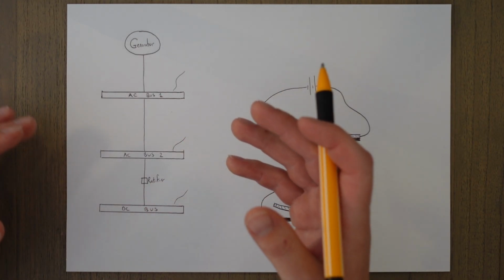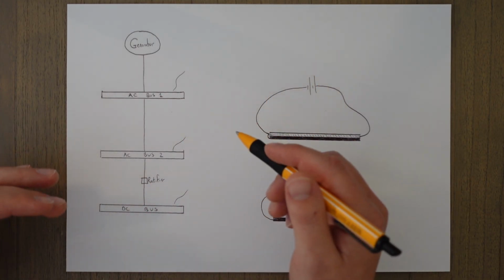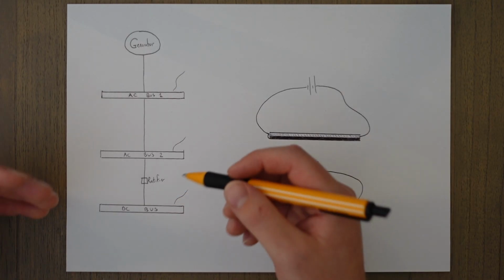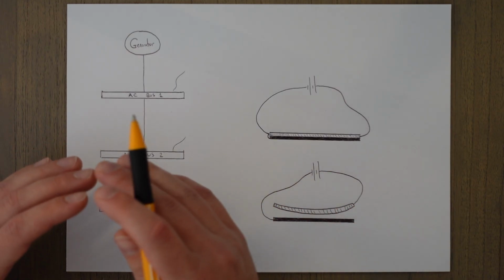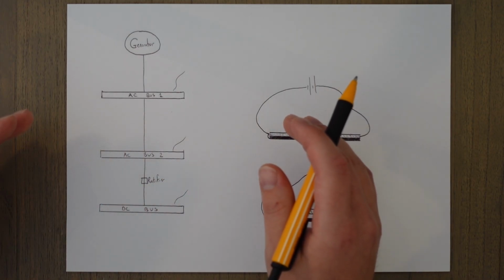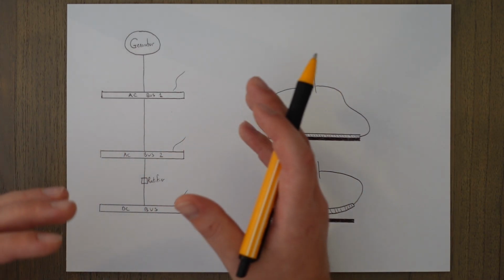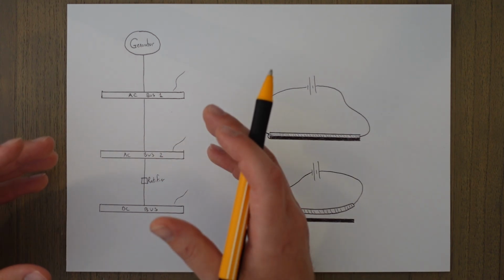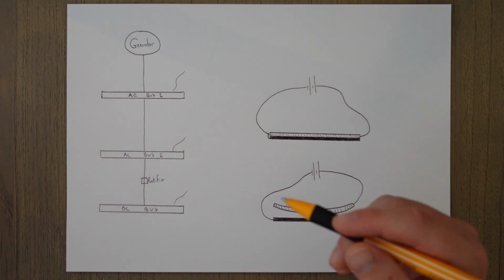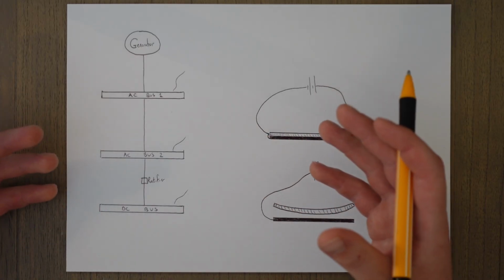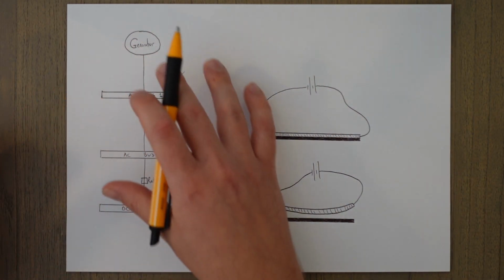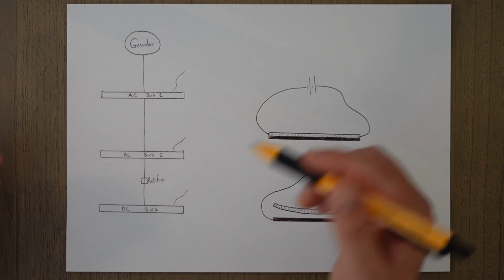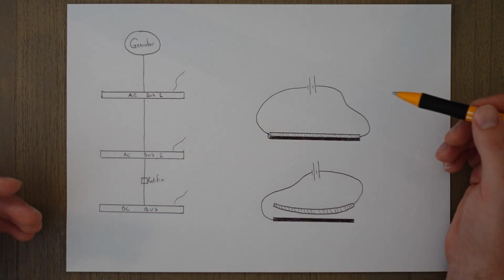For example though, if you were to lose all generators on board an aircraft and you only had a battery left to fly on, you might see something like one of the aircraft displays or radios no longer works, but it will always be set up to allow just enough systems left over to land safely, albeit pretty quickly before the battery runs out. If we don't want to ditch a whole set of systems at once though, we can use circuit breakers to control individual systems.